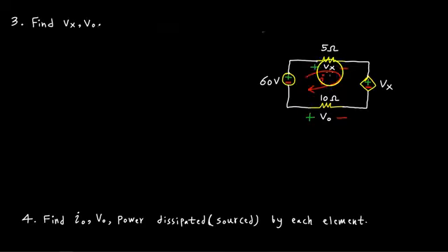So again, we're going to see that we have the current direction set. We have some voltages, some dependent voltage source, some variables here. So we're going to see that Vx here depends on this value, and it's already indicated that the polarity is in this direction. So let's go ahead and write our KVL now. I'm not going to repeat the same thing, so let's just go ahead and rapid fire go through them. So negative 60, oops, I don't want everything to be red.